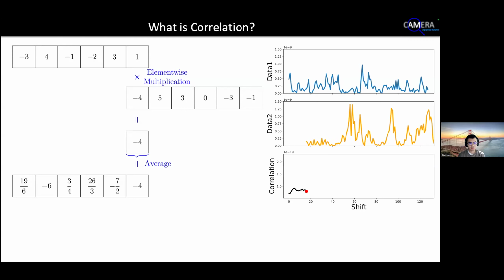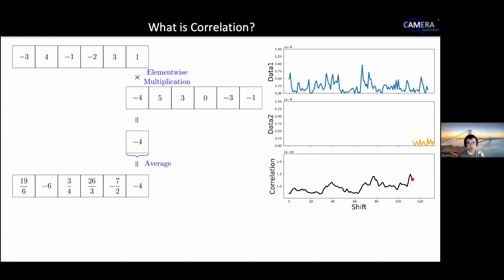So we can shift the function in orange to the right by a specific amount, and the red dot is shifted along with that, representing the current correlation value. And then we can keep repeating this. But actually, for continuous functions and continuous signals, we can shift the function to the right continuously to have the red dot plot a continuous correlation curve. So this move intuitively tells us how we calculate the correlation between continuous functions or continuous signals.